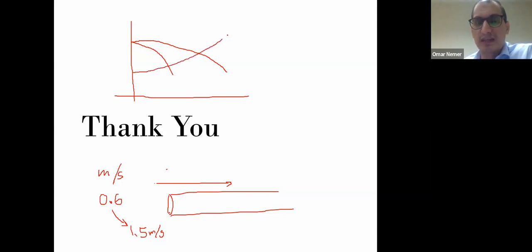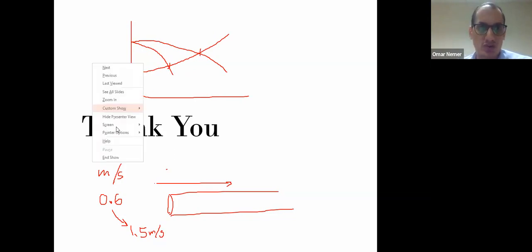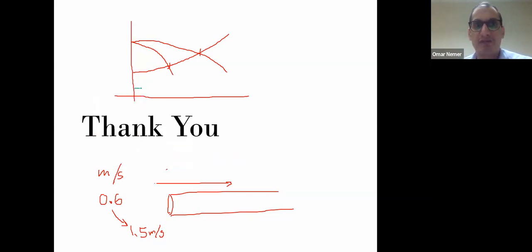The system curve will be like this. I have to make sure that there is an intersect between the system curve and the curve of the single pump and the two pumps. Because if the system curve was like this, the green one, this is the mistake. This will be the problem.